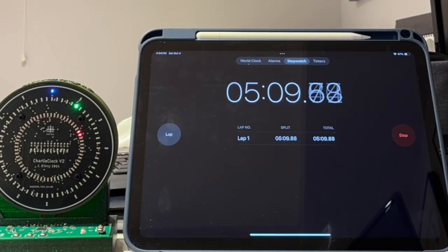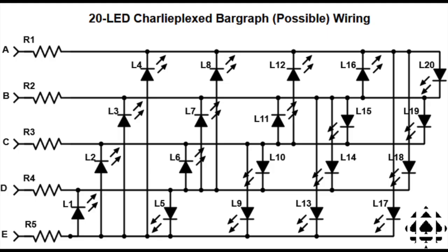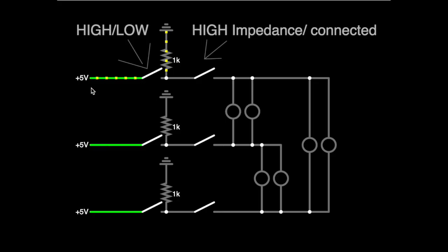When a microcontroller's pin is set as an output, it can be driven high, connected to power, or low, when connected to the ground. This actively forces the voltage level on that pin. However, when a pin is set as an input, it enters a high impedance state. In this state, the pin is essentially disconnected from the circuit and doesn't drive any voltage or current. It's as if the pin is floating or not connected to the circuit. This allows for external signals to be measured without interference from the microcontroller.